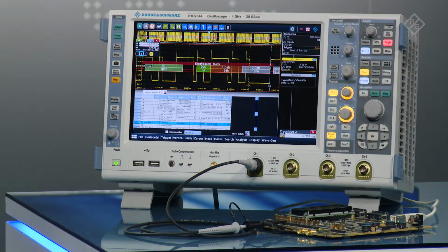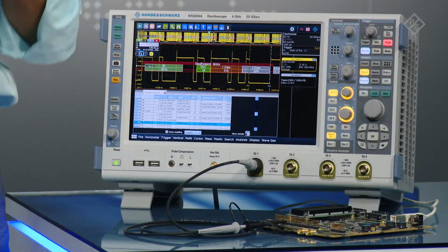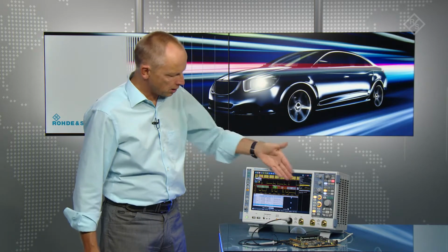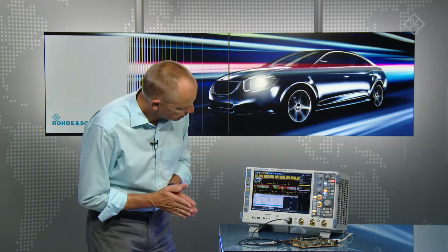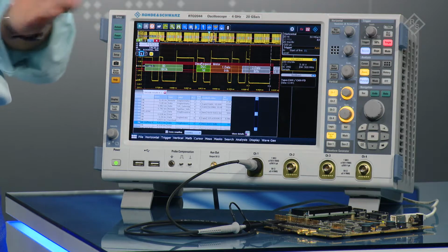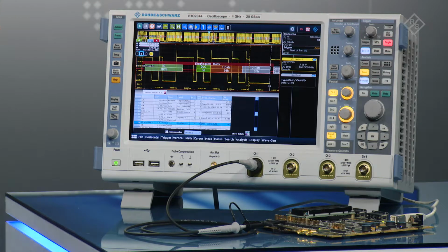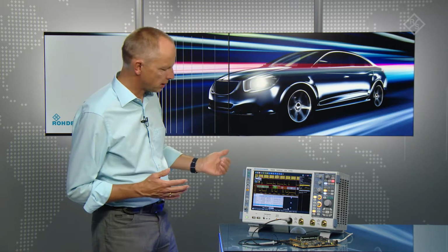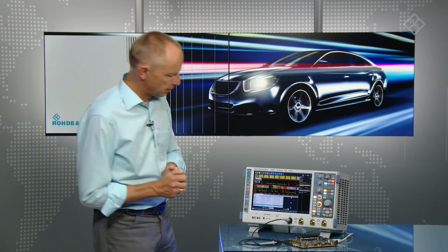You see we are at 120 microseconds, and this is actually causing the bit stuffing error, because now we have 6 consecutive lows or recessive. So this is causing the problem. So this specific bit. Now the next step would be to further analyze which one was the source address which is causing that problem, and maybe replace that one.